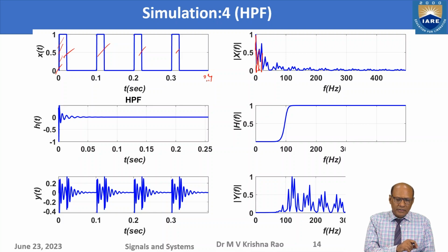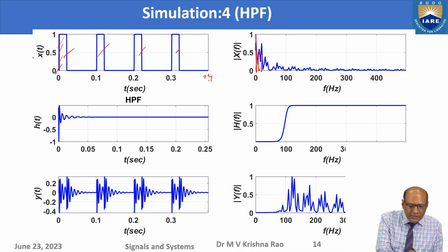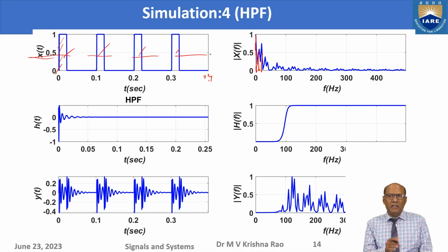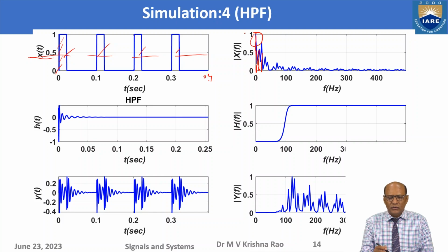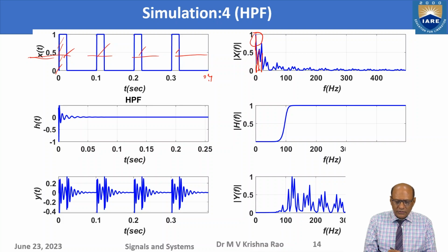And if I take this pulse to the center, let us say -1 to +1, or -0.5 to +0.5, if it is a bipolar signal, then this DC won't appear. So there is a spike at DC also. That is what you have here, and this spike you are not able to see in a single case because the energy spectral density is a continuous spectrum, and this is a discrete spectrum, or line spectrum as we call it, and you are able to clearly see this line.